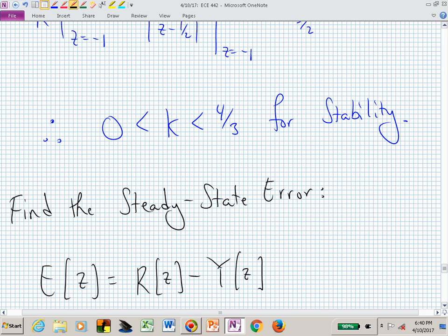What's one quick way, if you're running out of time on the exam? You've got a PI controller. Are you assured that this system is stable? You could say, pick k equal to what value for stabilizing the system? I would probably pick something bigger than 0, because 0 would put one of my poles at 1. So I want to put it a little bit higher. Maybe I say k equal 1/4.